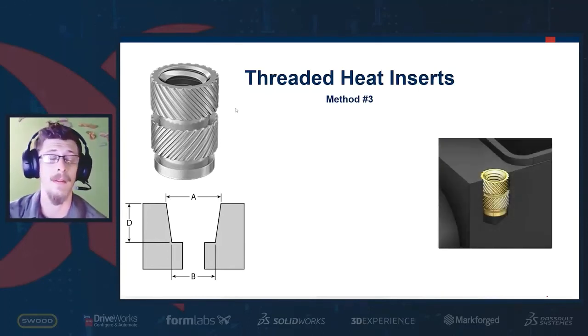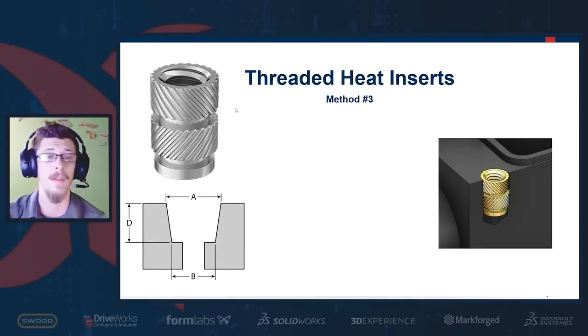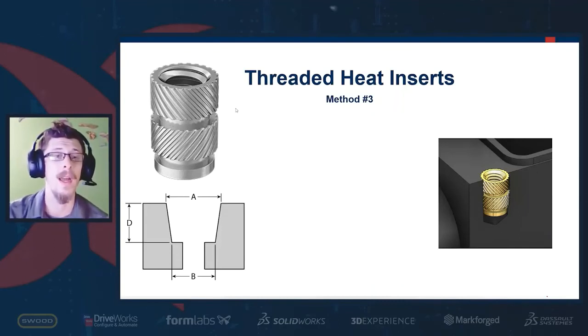When adding these threaded inserts, it is key to have enough material for them to grip and fuse to. So there are settings within your print that allow you to increase the wall thickness. So it could be something between 2 or 3 or 4 wall thicknesses, maybe more. If you think about the size of our nozzles, again, 0.4 millimeters, and then every wall is 0.4 millimeters. Just make sure that you have sufficient material so that when you insert your heat threaded insert, it grips into the material and can melt sufficiently without going into the hollow cavities of the infill of the part, because then it's not going to be strong if it makes contact with those hollow spots.